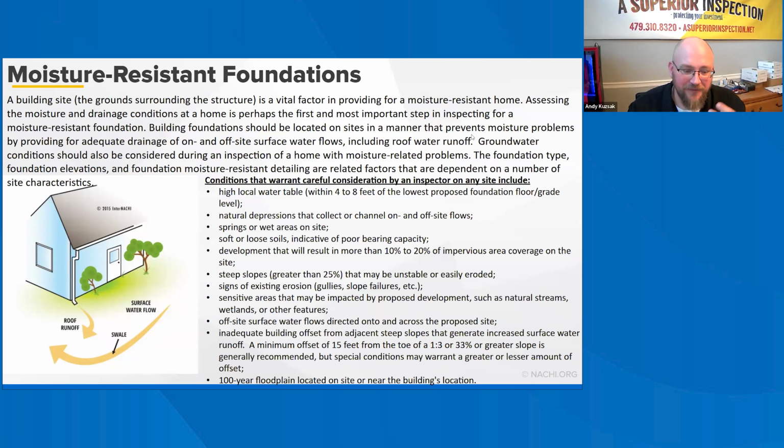So if you can find the model number of the window and there is any question about how it was installed or whether or not it should have a certain type of flashing or if it should have sealant applied around the exterior, definitely do your due diligence, do some research, and see if you can find out how it should have been applied and whether or not it is missing something.